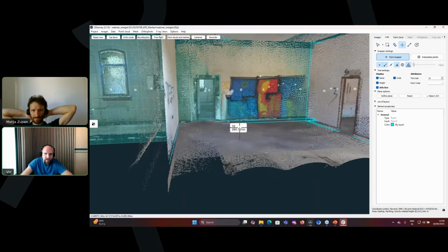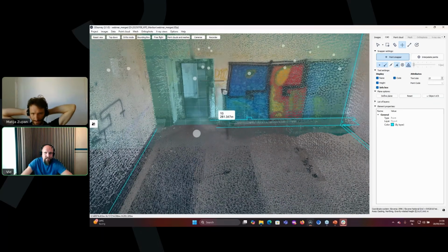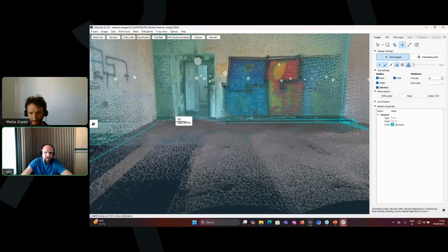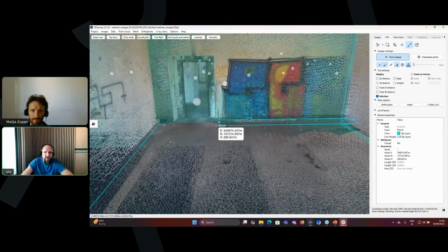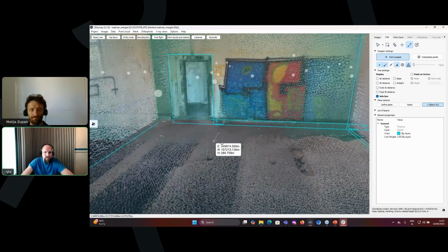And then, for example, if I wanted to draw this door here, I can now do that. First go into line drawing, click here, enable the object UCS. Then this will be the height of our doors here, and it will go to here, and then back down to this. We will snap on this point, move it here, and this is now our doors.